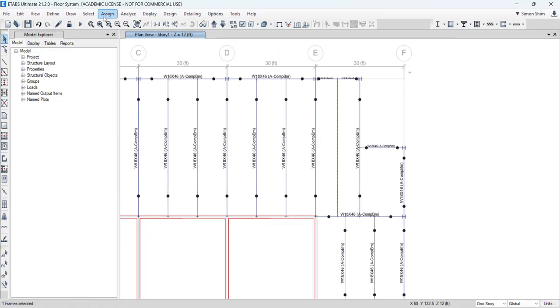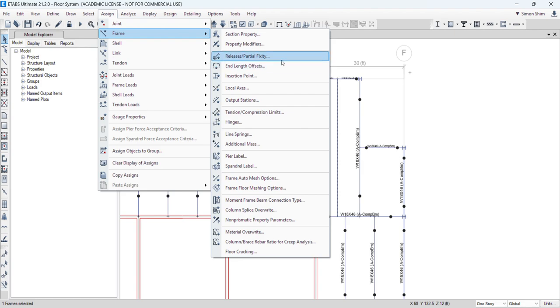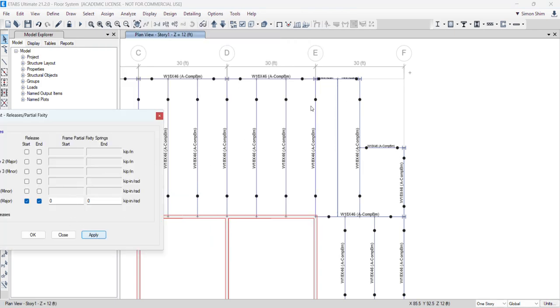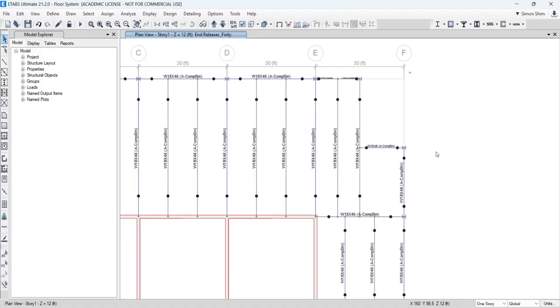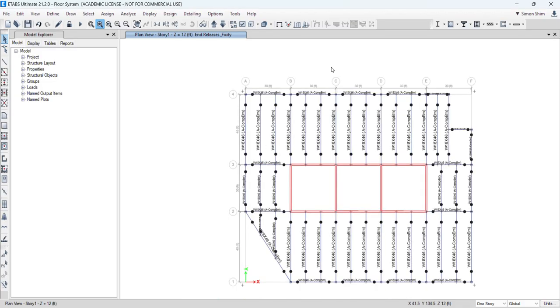So I can add another beam here because I told you that typically the metal deck span is about 10 feet. So beam and beam, and we have a little bit less than 10 feet spacing of the beam. All right, so this is kind of a variation you need to know.